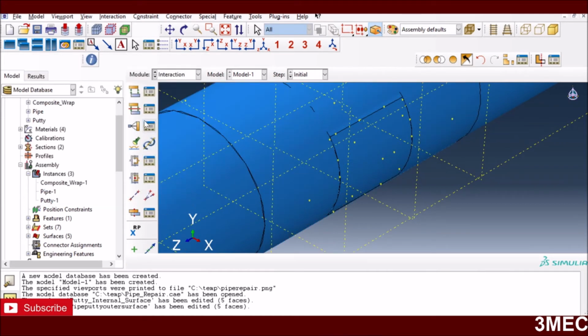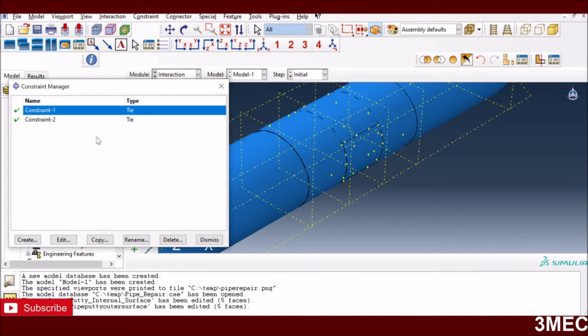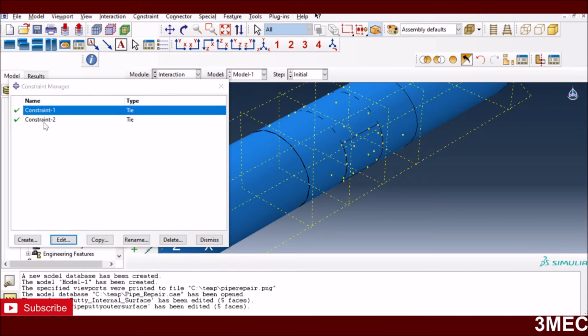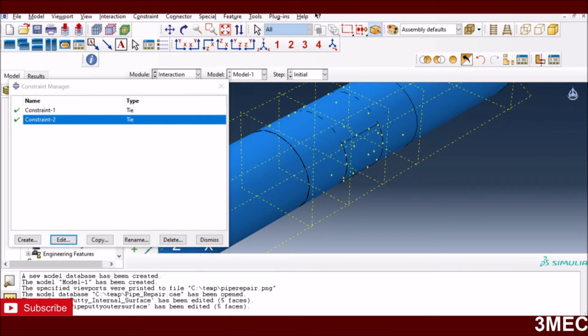So now once I have defined all the surfaces, I don't have to worry when I select the interactions, because then I can select it from my names. So I go here, and you can see there are two tie constraints. One is between putty and the pipe, and the other one is between the pipe and putty surface with the composite wrap. So this is the interaction between the putty surface and the pipe, and you can see I selected the two surfaces, which is defect surface and putty internal surface. While the second one would be, you can see, the surface between the pipe outer surface, which is along everything, and the putty and the composite wrap internal surface. Okay, so that's what we have done here.